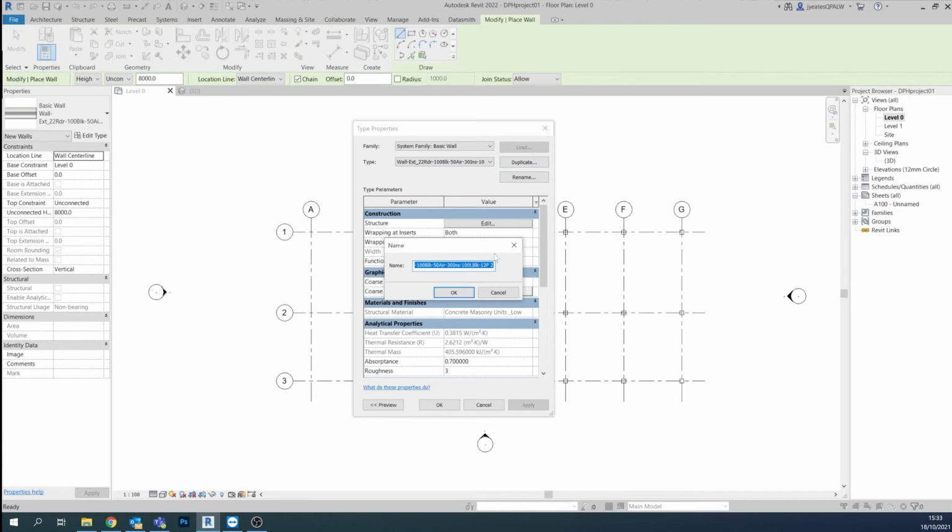So again, I'm going to duplicate this wall and make some changes. So our wall is going to be, at the end, 12.5 on the plasterboard. It's going to be 100 block work. It's going to be an increase of 50 on the insulation, and the air gap is actually going to be a very specific 57.5. Accuracy is really important. Okay, and then 100 mil on the block work, and we're going to have 50 mil on the render. So 50, there we go.